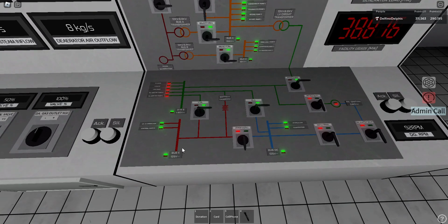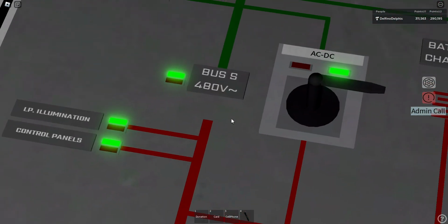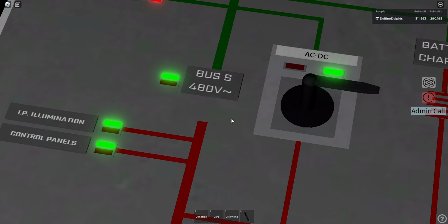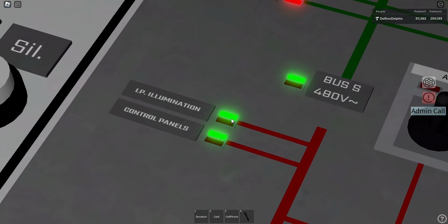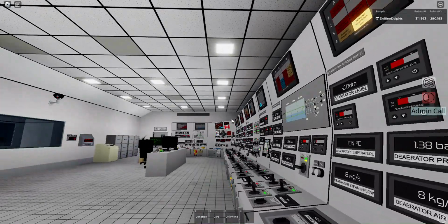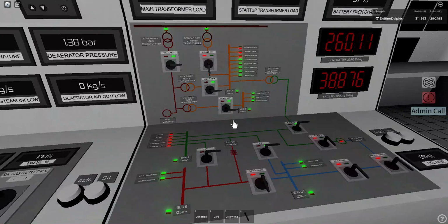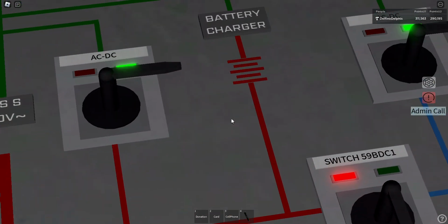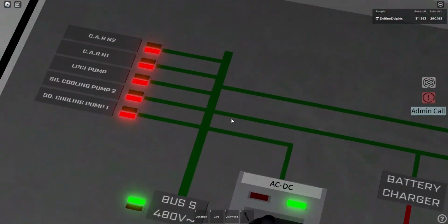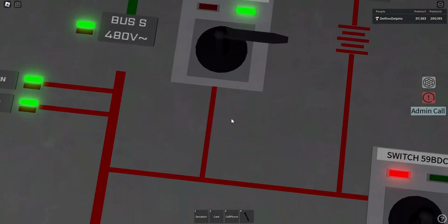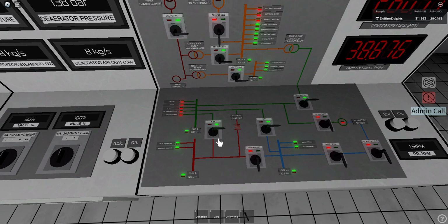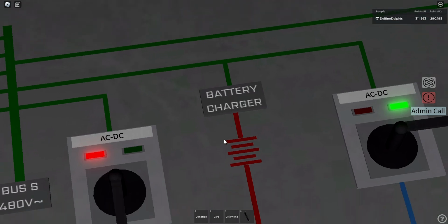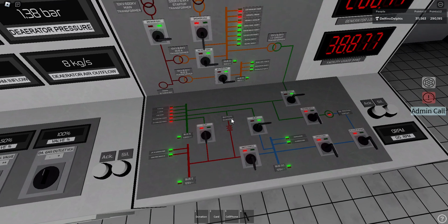And the last bus, the red one, this is the emergency bus. This bus is used basically to power the panels, and it gives us these emergency low power lights. Normally it's powered again from the safety bus via this rectifier switch, but if you turn it off, it still stays on because it has a battery here, so it never goes off.